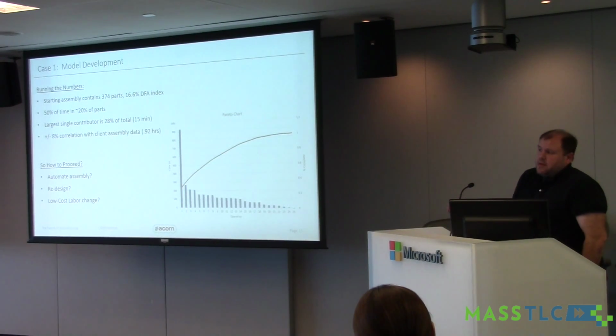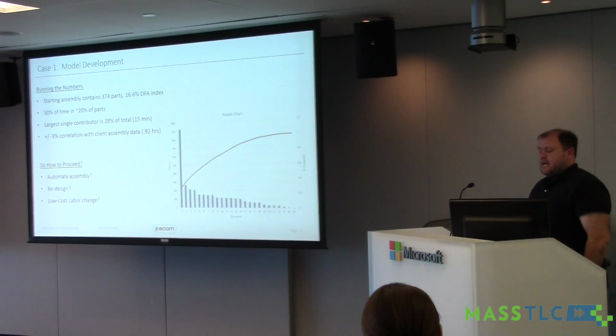And we did this model kind of blind. Our customers like us to do that. We hate doing it because we always like to know the answer before we do the analysis, but we actually ran through it and came out about 8% off from what their actual takt time was on their current assembly process. So pretty good resolution on predictive modeling works with what they actually get. So it took them about an hour to do the overall assembly.